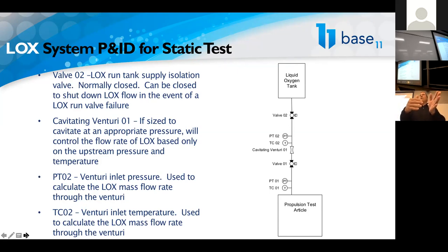Okay, and once you choke the flow rate through the orifice, it depends only on the upstream pressure and temperature conditions. So you can have a sonic venturi that's choked, and if you've got 1,000 psi coming into the venturi, the pressure downstream of the venturi could range from vacuum to 800 psi, and the flow rate through the venturi would not change. So you can completely decouple the flow rate from anything that's going on downstream.